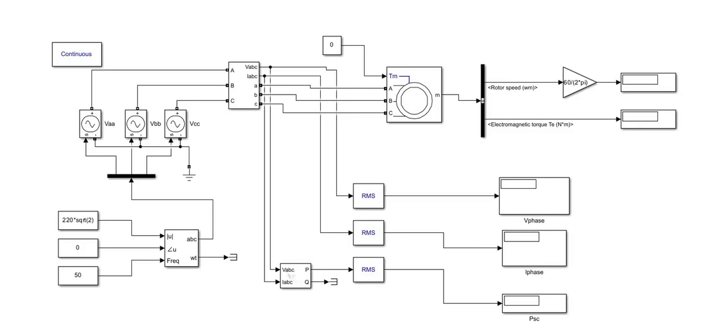So for test 3, we're going to do the no-load test of the 3-phase induction motor, which is to measure the value of the magnetization reactance XM, the stator copper losses, and the rotational losses of the motor.